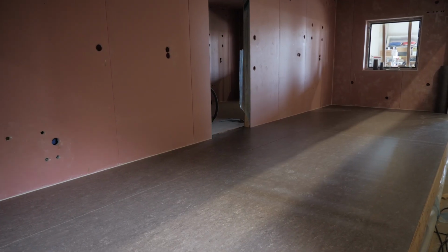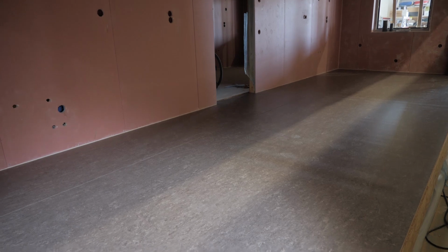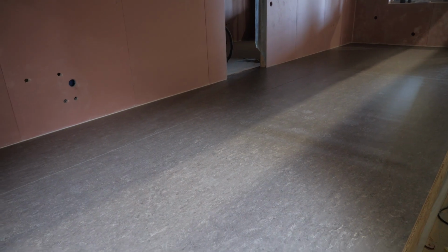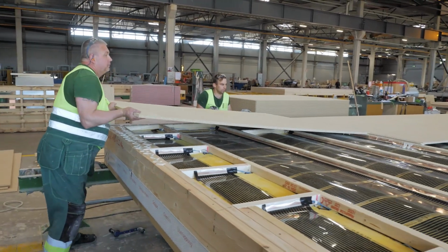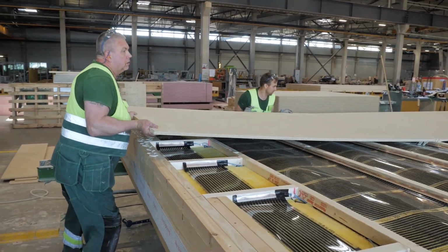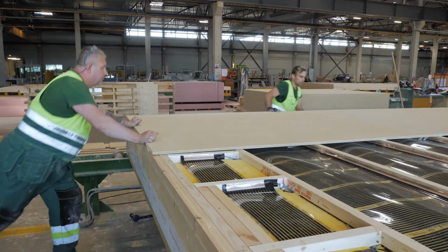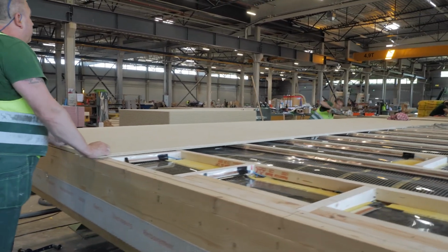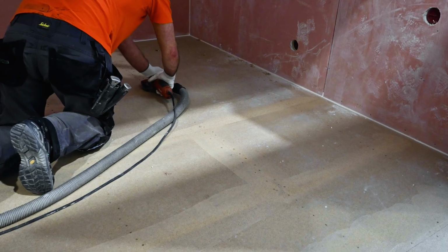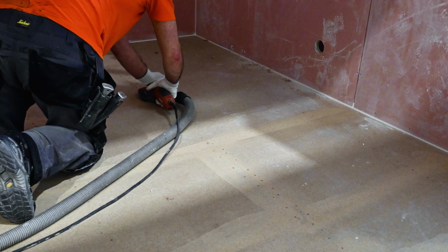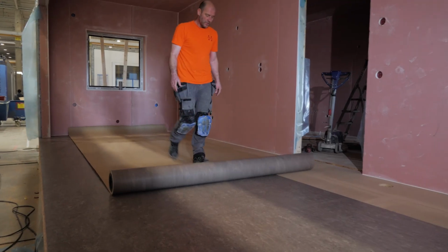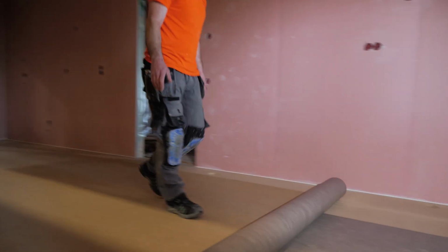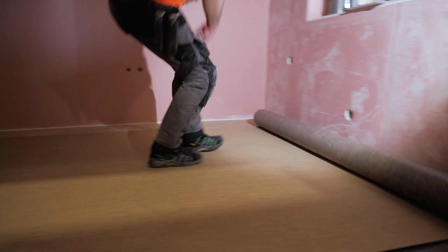For roll-based floor coverings, the subfloor must be rigid and flat to prevent visible irregularities. The subfloor can be made of special gypsum board, a poured concrete slab, or a wood-based board, onto which the roll material or other intended material is glued. In case of unevenness, the subfloor must be sanded. Before installation, the material must acclimate in the room for at least 24 hours.